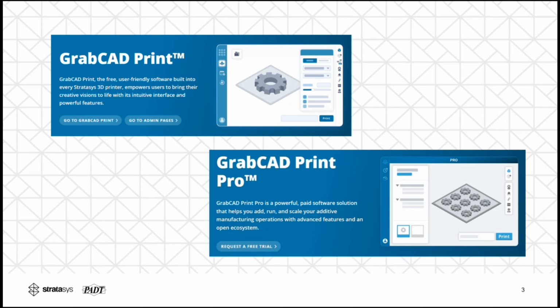GrabCAD Print, commonly called GrabCAD or just GCP, imports more than 24 3D file formats, making it easy to bring in and manipulate models generated by a wide variety of CAD packages or produced through different 3D scanning systems. GrabCAD's standard version is also completely free. Anyone can download it and set up parts to print based on an Origin 2 template. This offers a great way to evaluate and learn the software long before owning the hardware. Any print files created with the free software can be saved and uploaded to print on any corresponding Stratasys printer.